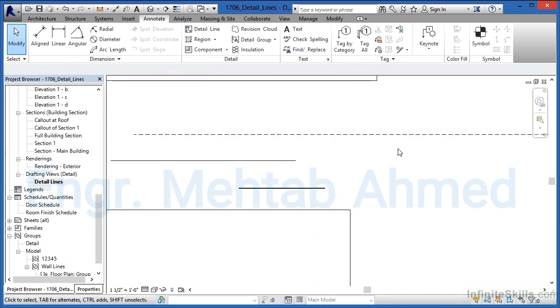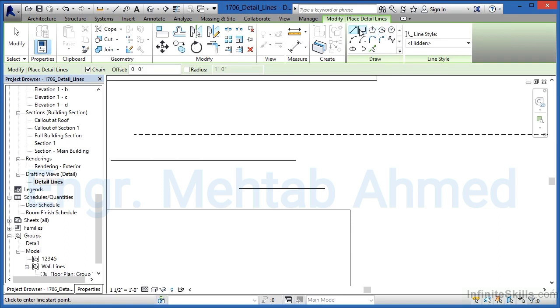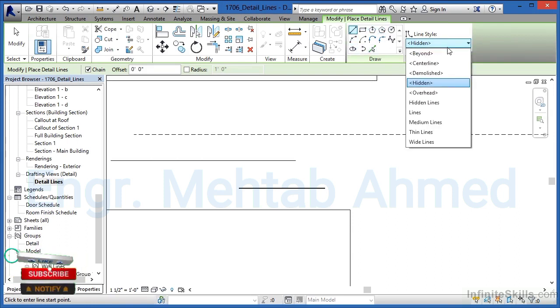To draw in different kinds of line work, circles, rectangles, all those different shapes, you need to come underneath the Annotate tab, be inside of a flat or two-dimensional type of view, select Detail Line, pick which shape you want, then here where it has Line Style, pick the line style with the appropriate line weight, as well as line type, and then start drawing in your different lines.